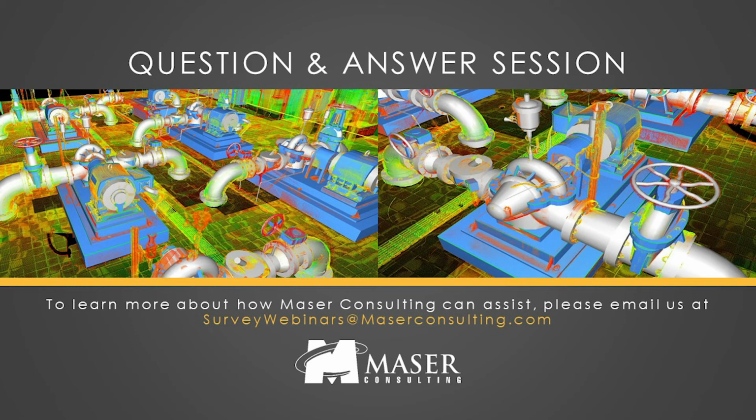So the way you would visualize scan data in Revit is by using Recap. Recap is a standalone visualization tool for scan data, developed specifically by Autodesk, I believe, for Revit and Civil 3D. What you would do is link your completed scanned point cloud from your Recap file into your Revit model, using various methodologies to make sure that it's placed correctly.